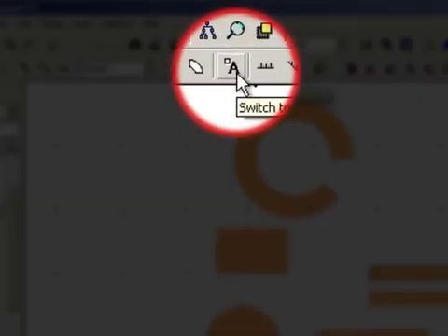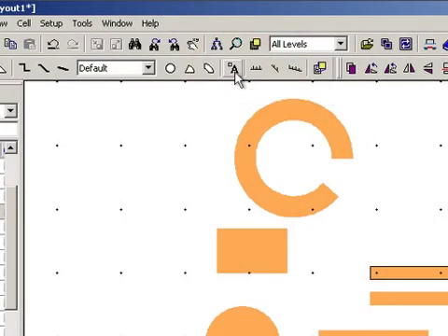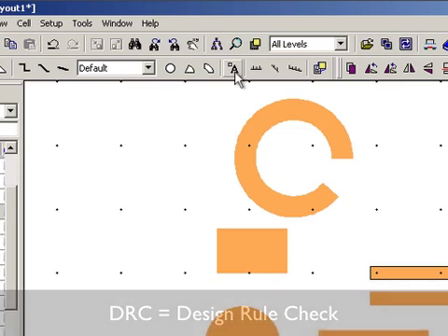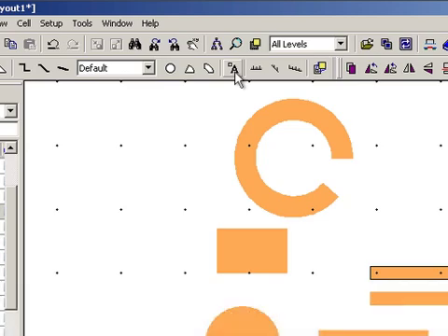So moving along to the right here, the next icon that we're going to come across is a port labeler. Now, LEdit itself is one piece of a larger software package provided by Tanner Tools, and LEdit stands for Layout Editor. In conjunction with the other tools, it does offer quite a few powerful features that we don't harness. For example, you can do net listing, 3D modeling, parasitic extractions, LVS, DRCs, all kinds of good stuff. In essence, we really only use it in its most basic form to draw geometries.